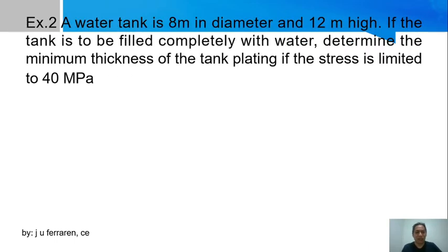Now, suppose you are given a water tank having a diameter of 8 meters and a height of 12 meters. If the tank is to be filled completely with water, determine the minimum thickness of the tank plating if the stress is limited to 40 megapascal.